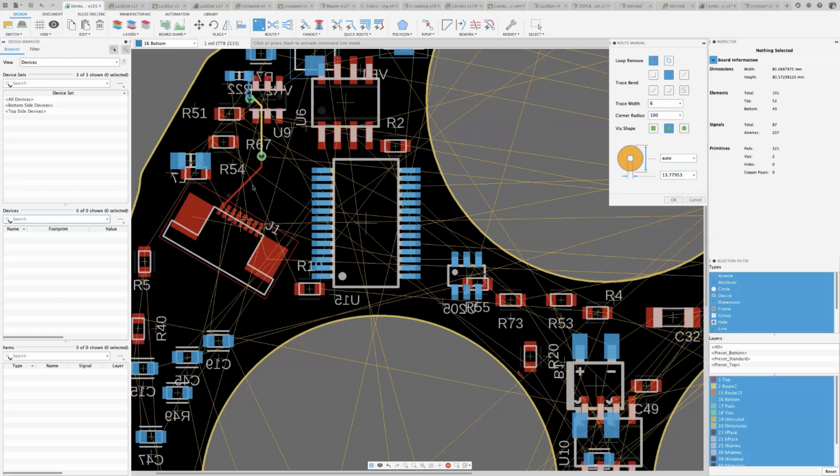So I could go ahead and select any of these components that we have here, any of these signals. Let's say, for example, we select here and go with a short one. Now, a nice thing that we have, I'll go ahead and cancel this for now, is the setting down here in the bottom panel. I could do walk around violators, ignore violators, or push violators. So I'm going to just start here with the walk around violators.